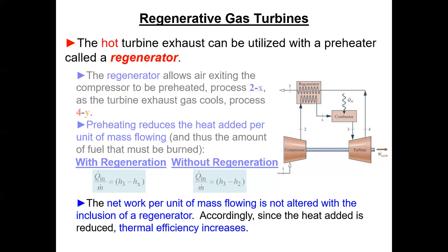Now the output is not changed. We haven't changed anything on stage 3 or stage 4. So we get the same work out, but we're going to put less fuel in, so the efficiency has to go up. This will enhance the thermal efficiency.